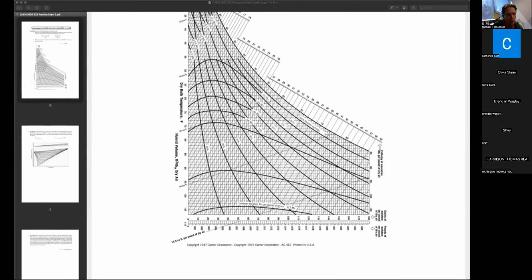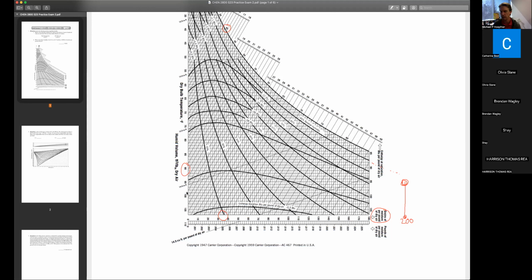And then the outlet conditions are 40 degrees Fahrenheit, and just based on the mechanism, that would be at 100% humidity. So we can go to 40 and 100% humid, and we draw down, and that would be this other number here, that's 30 something. Does that make sense? Does that answer the part of the confusion?